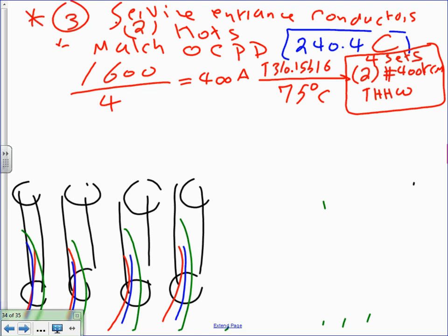Oh, why didn't I use the 310.15(B) little table? Because we're paralleling, guys. The actual service is 1600, not 400. We're paralleling. Then why would it be 400 kcmil? Wouldn't it be 600? Who told me that? I'm sorry. Okay, whatever the table gives you. Is it 600? Thank you, 600 kcmil. I see the confusion. Absolutely. Whatever 310.15(B)(16) gives you, 600, under 75. Good point.